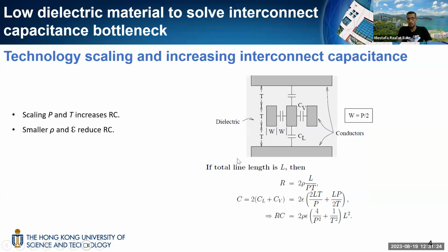This increase in the interconnect density requires a reduction in the metal line length and also the dielectric thickness, and both increase the metal line resistance and the dielectric capacitance, and the overall RC delay is increased. For ultra-scaled technologies, the RC delay is even higher than the transistor delay.